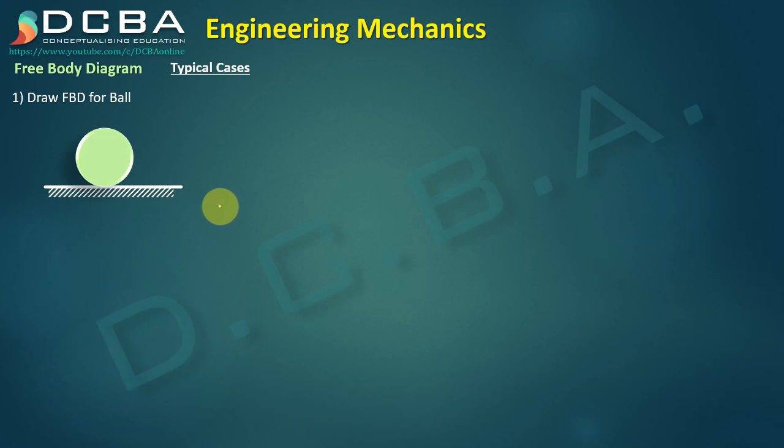Now there are certain typical cases where we will see how the free body diagram is shown. First is to draw the FBD of this ball which is resting on just a surface. So what are the different types of forces? First we should think about what are the different forces that are acting. Now here let us say that no external force is acting on this, so applied force is not there. Second, we have the non-applied or inherent forces, which is the weight. So weight is there, and then the reaction is there from this surface. So if I want to draw the FBD of this ball, this is the FBD, simple.